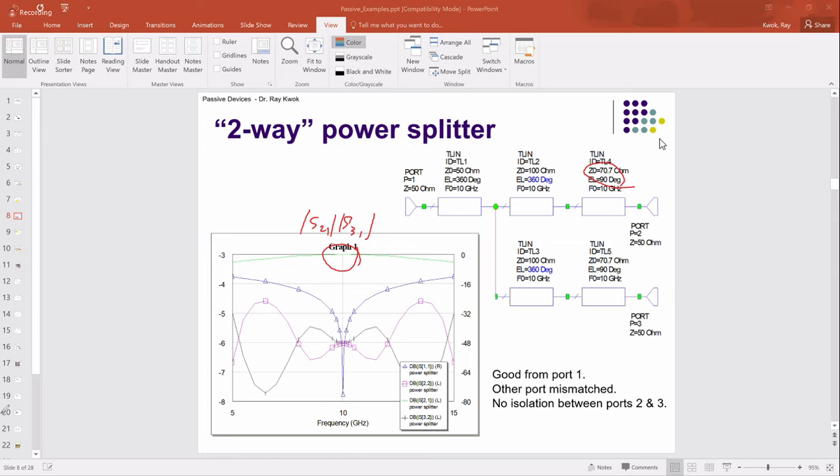So the left axis are S21. Here you can see the green, it says dB S21, left side. You see the L here, the left side scale. So you read this at the left scale as -3 dB, which is what it's supposed to be. You want the power to be equal split, so it's 3 dB each, at that frequency. Are you with me?